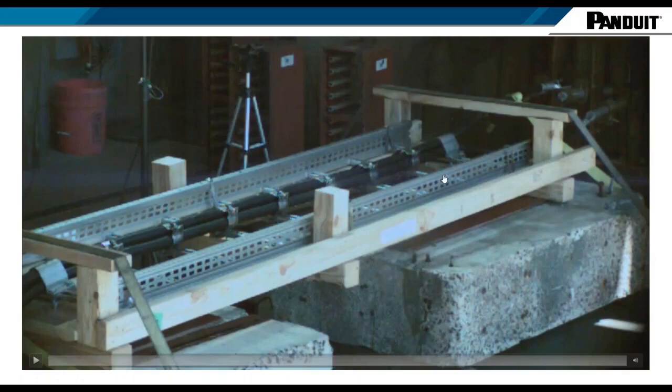What we've got to do to meet the IEC requirements, we've got to carry out that first short circuit test, and we've got to hold that decaying RMS fault for 100 milliseconds. So as well as the initial forces at peak, we let that RMS diminish until it almost gets to a steady state, but we've got to hang on to that RMS for 100 milliseconds. To meet a class 1 test, we are allowed no loose or missing parts, and we cannot damage the cable. We cannot damage the jacket of the cable. Any damage to the cable, any loose or missing parts, we fail.